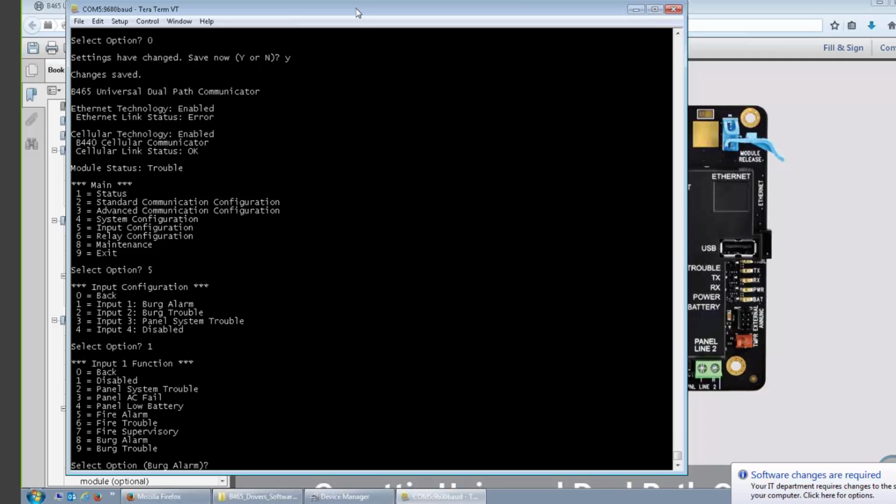Yeah, because I get a lot of calls on something instead of putting in like a 5-zone panel, just to have a little 2-zone panel with automatic dial out would be great. Well, something that just occurred to me is that this isn't going to have any kind of an output to activate sirens and things like that. There are relay outputs, but they're not going to support any kind of supervision or anything. So I would say no, it probably would not be used for a standalone. Okay.